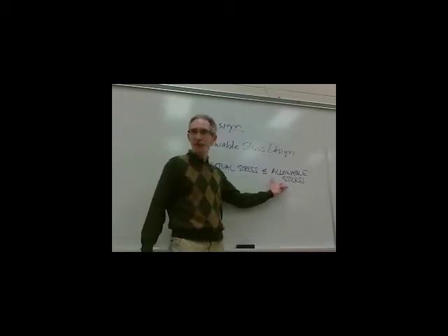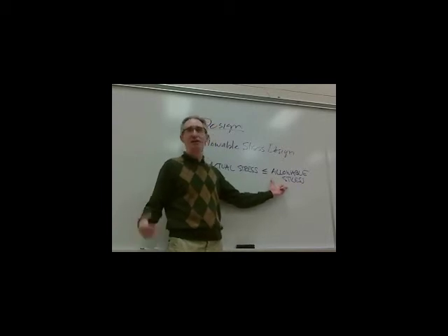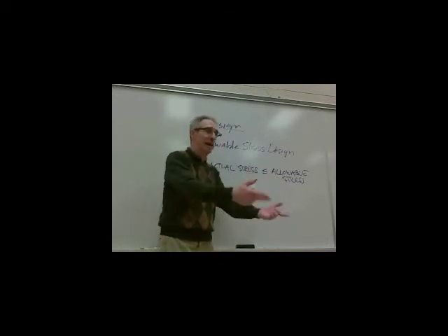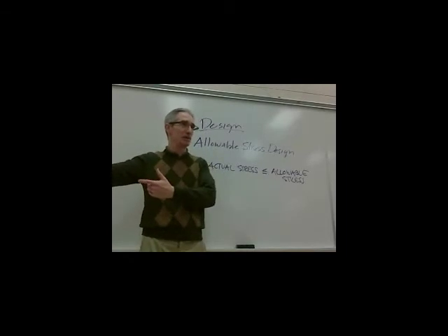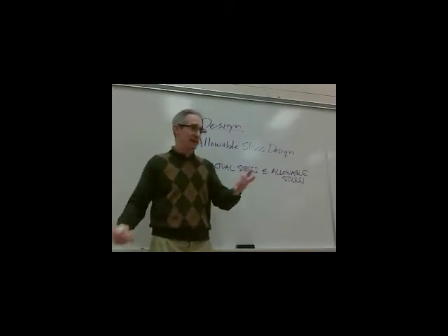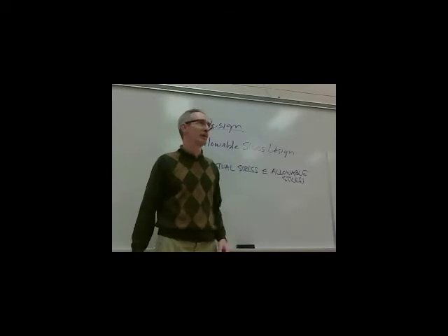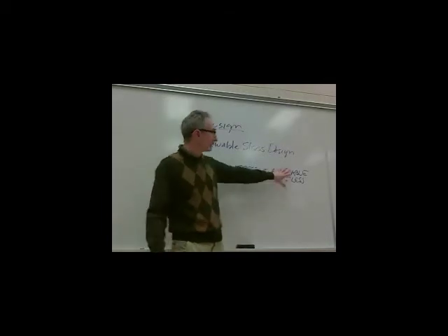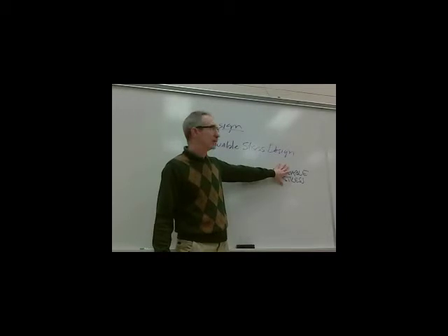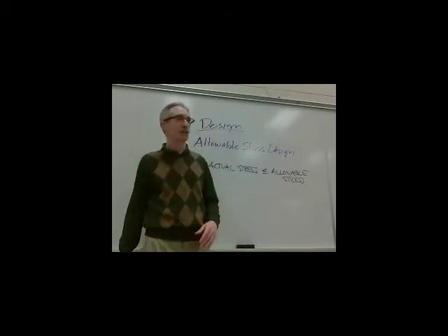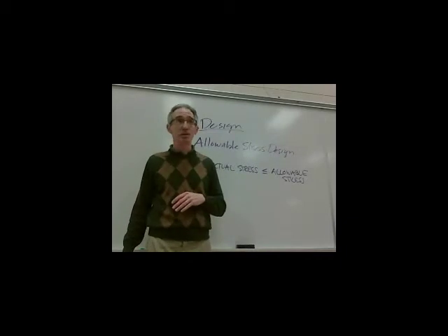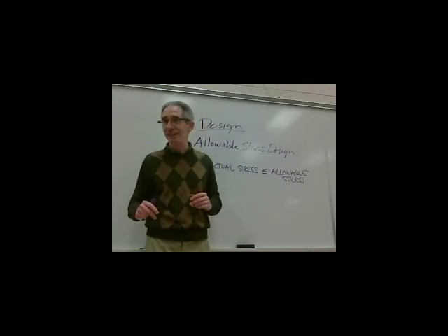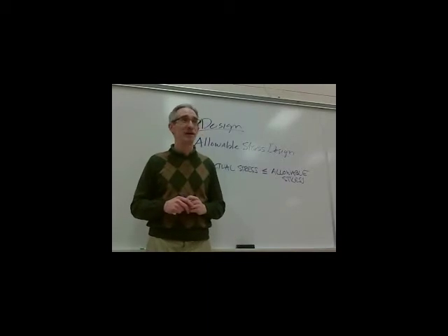Biggest thing people have trouble with is they say, well, where do you get allowable stress from? Well, allowable stress, like I said, is given by a code, or given by an expert, or given by a manufacturer. Okay? You might get into designing foundations, and the way you get the allowable stress is the soils report that the geotechnical engineer gives you will say, hey, for this type of soil, the maximum or allowable bearing pressure, bearing stress, is 4,000 pounds per square foot.